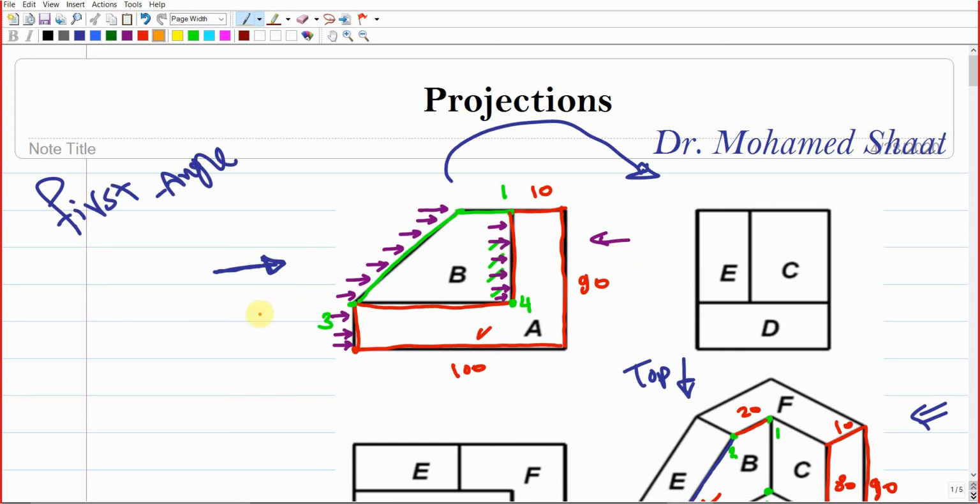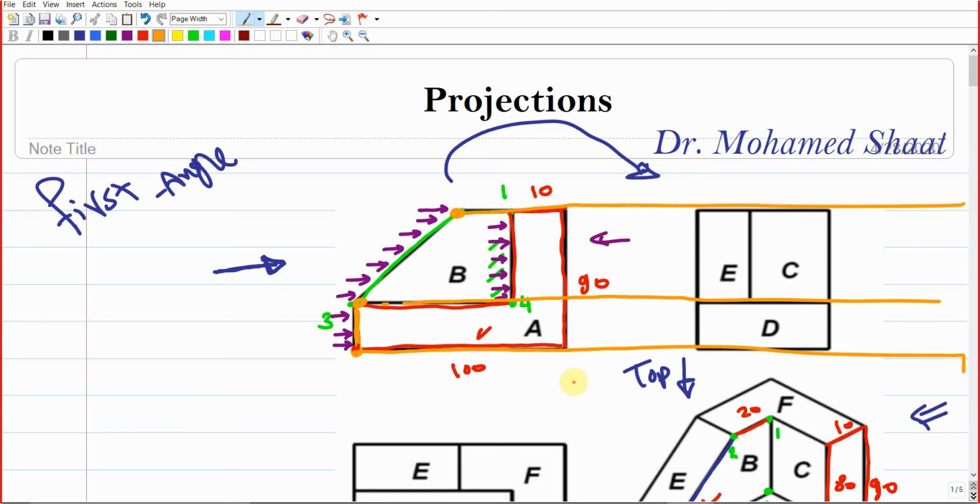So your objective is just to pick a point. If you look at it, we do have one point, another point of these lines. Like we do have a vertical line here. This vertical line should be projected there in the side view. So you're gonna draw a very light line. Extend this line, and this extension line should be barely seen. Then extend this point into another line, and do the same, this point will be projected into another line. So do you see this maximum height? This should be the maximum height of the side view that you are going to generate.